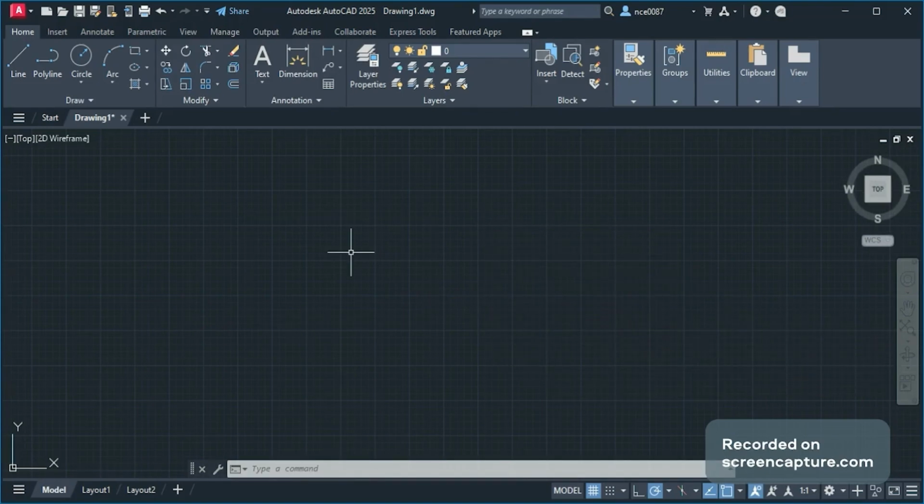The polyline command is a command tool used to draw 2D polylines composed of lines and arc segments. To use the command, type PL on the command line. Specify where the first point of the polyline is. Specify where the end point is and press the spacebar to end the polyline.